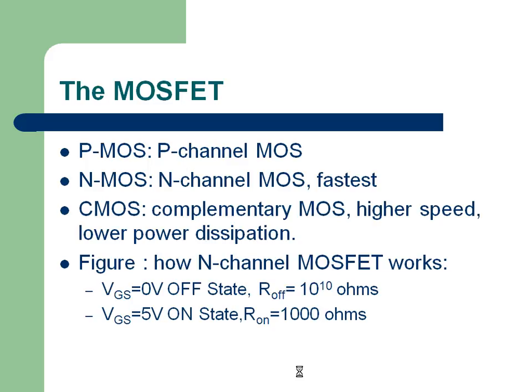Now coming to typical numbers. If you are looking at an N-channel MOSFET with gate-to-source voltage of 0 volts, it is like an off transistor, and the resistance is of the order of 10 gigaohms, very high resistance. It is equal to an open circuit. Whether that open circuit is high impedance or not depends on what the other side is. Because you used the word high impedance, I should explain this.